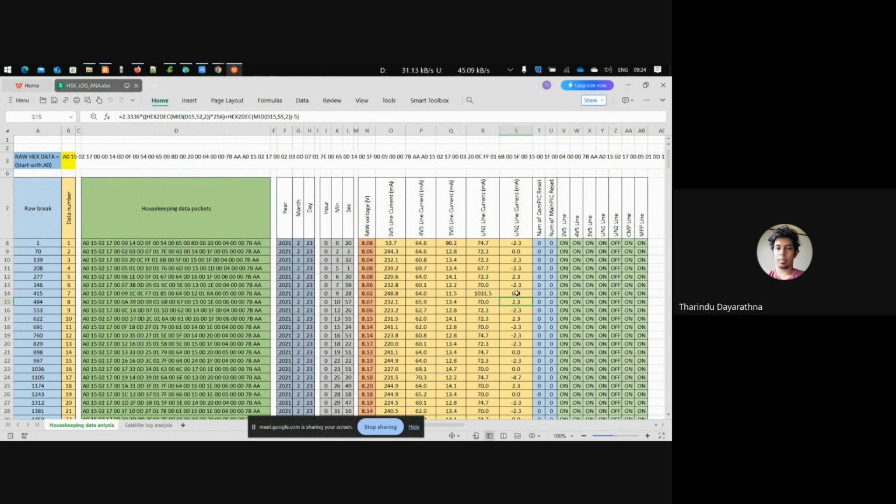Let's say a 20 milliampere error. Oh, that is not okay. So you have to do something for that one. That's too much. So to do something, you have to do the calibration.